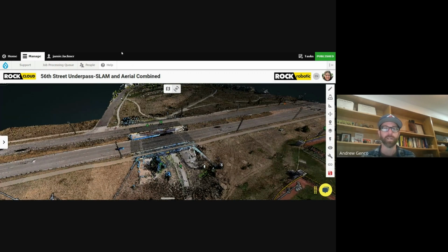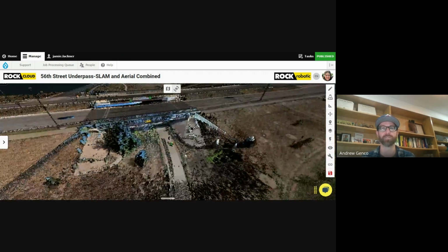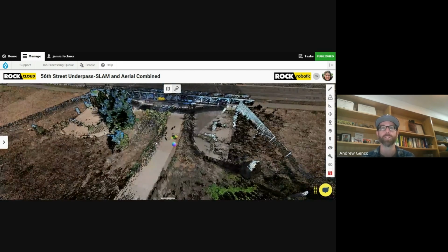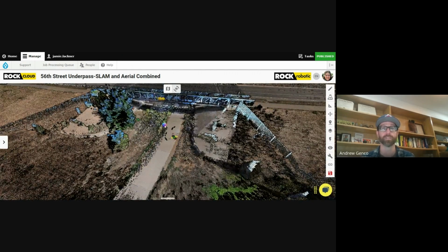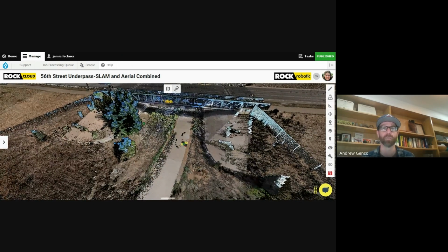So now I'm going to get into the actual ground control placement for this site, just because with merging of airborne and SLAM, it really had to be taken into account. We wanted to make sure that at the end, our SLAM data could align with our airborne data. And so for that, proper GCP placement for tie-in using the common coordinate reference system was paramount.